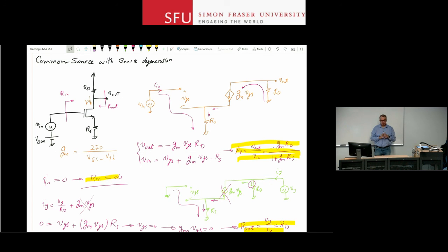The point to remember here is that even if you don't want to solve it using AC circuits, if you're unsure when you see the circuit whether it is really the common emitter that you saw before or not, or whether it is really the common collector that you saw before or not, you can always, always, always go back to small signal analysis, draw the small signal model, and solve the circuit that way.